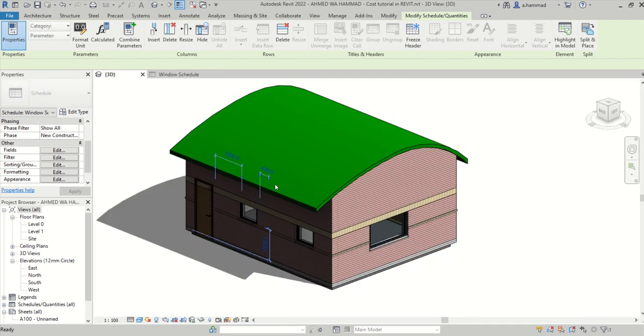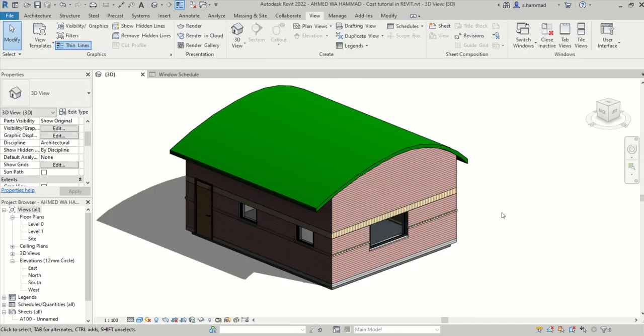So if I go back to my project, and if I want to estimate the cost of my walls, note that there are two ways I could do it. Number one, I could do it through just associating a total per meter squared cost, and that would consider the cost of labor, the cost of materials, etc. So it's a combined per meter squared unit cost.